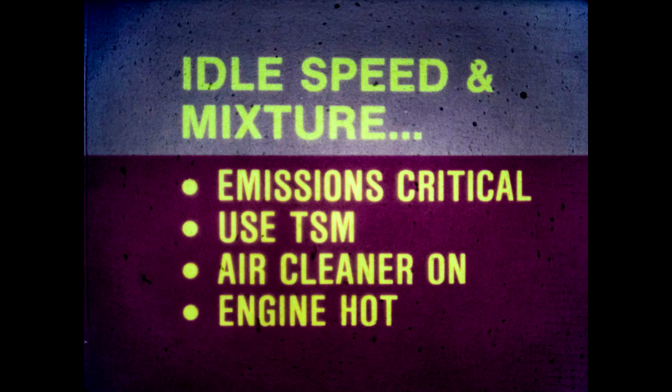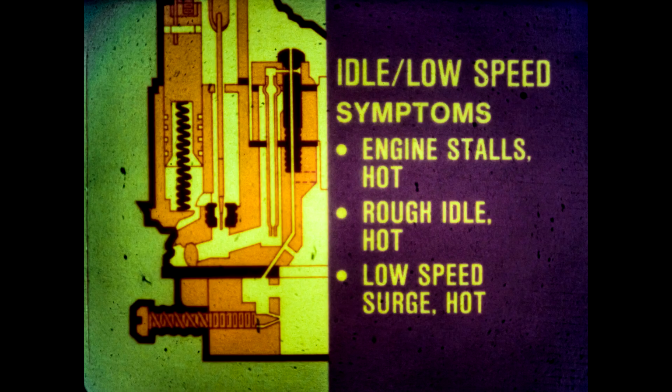Be sure to remember that idle settings are critical on emission-controlled engines. When performing this service, always use the technical service manual for idle speed and mixture setting procedures. Here we see some typical symptoms that may occur at idle or low speeds. Note that these symptoms relate to a hot engine. Cold engine symptoms are discussed later.